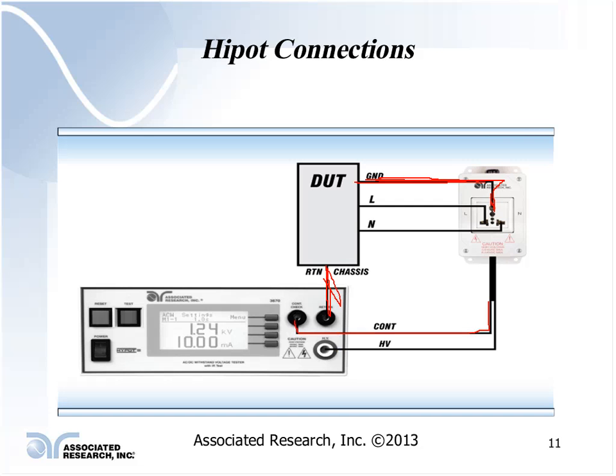So I'm making sure that this item is in fact grounded through its line cord or through the IEC connector or whatever. I have to check that circuit for continuity, and we normally will go through and do that test.